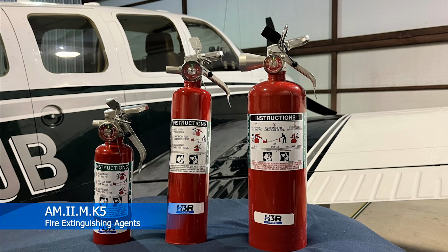Halon has been the fire extinguishing agent of choice in civil aviation because it's extremely effective on a per unit weight basis over a wide range of aircraft, meaning that 1 ounce of halon is going to put out a lot more fire than 1 ounce of water or CO2 or whatever. So you'll see halon over and over again in aviation throughout the years.